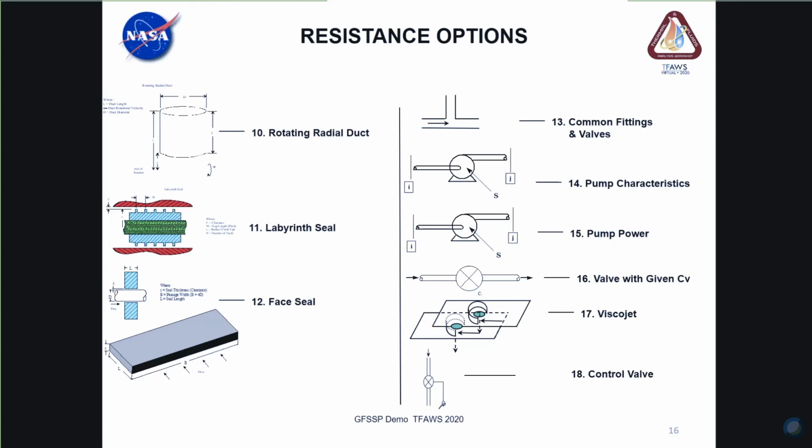That I'm not too certain of. We've only done a limited number of models where we've compared solutions. Our example 3 shows flow in a converging diverging nozzle, and it agrees pretty well, gets the flow rate pretty well, and it predicts at what point the flow is going to choke, at what pressure ratio, upstream over downstream, it's going to choke. But we haven't really done any detailed comparisons of high-speed flows.